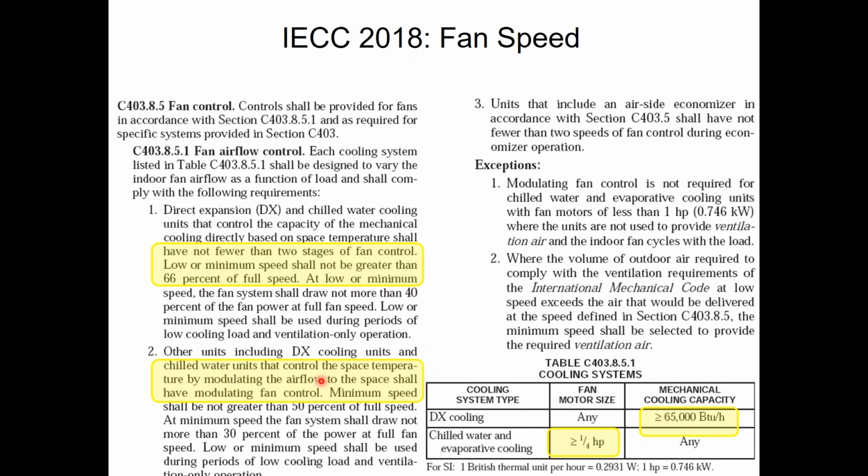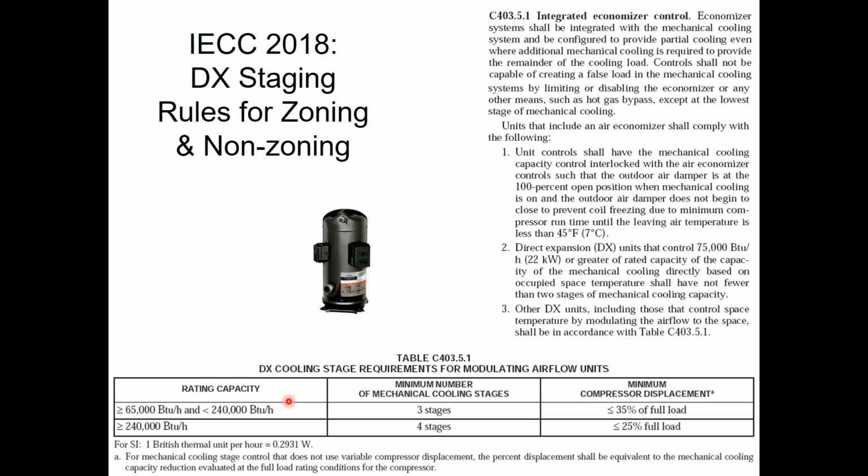So because of the new code, you actually have to have on your rooftop a VFD on your VVT system. And you still got to put the bypass in because the VFD probably can't back down far enough for your smallest zones. So you got to put a bypass in as well for when the VFD is throttled back as far as it can go to keep the equipment online, then the bypass can take care of the rest. If you don't do that, then what you have to do is put minimum damper positions on your zones, which, unless you've done a good job of laying it out, could be a problem. So keep that in mind. Make sure you're putting VFDs or some kind of modulating fan control, but I don't know why you would do something other than a VFD on your VVT type projects.